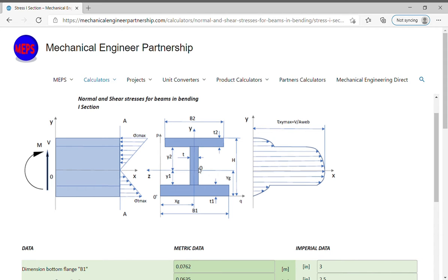On the graphic of shear, we observe that the shear stress has two values for sections situated at y1 distance, respectively y2 distance. Generally the stress due to the combined bending and direct shear stresses is maximum on top or bottom of the shape, but in certain situations can be maximum in sections at y1 and y2 distances.